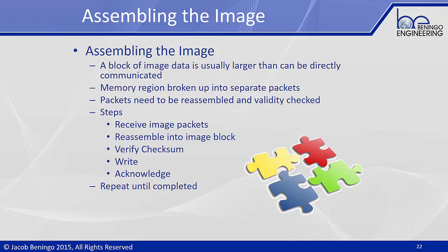Now, as I mentioned, the bootloader is going to be assembling the image. So if we're command-driven, we can't store the entire application in RAM or flash at one time. What we're basically going to do is chunk up the application and send it down one piece at a time. So we've chunked up the application into smaller records, and we're going to send those records over one at a time to the microcontroller.